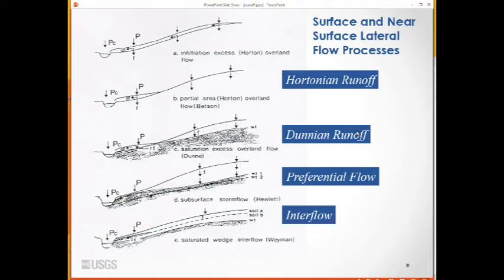The second graph illustrates stormwater infiltrating upslope, with some water infiltrating and some flowing as Hortonian runoff near the bottom of the hill slope. This is a partial contributing area process and is used to compute Hortonian runoff on pervious areas. The third graph illustrates saturation excess Hortonian runoff, where upslope stormwater infiltrates and near the bottom of the hill slope water is discharging to the land surface.